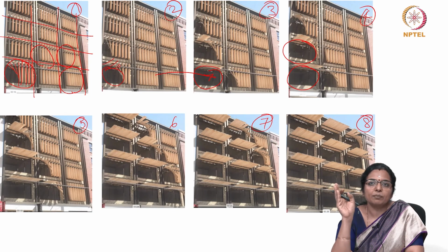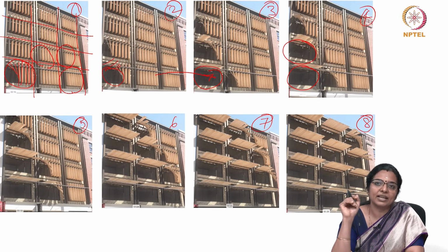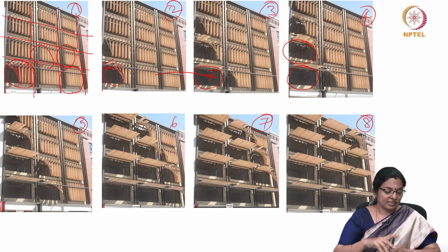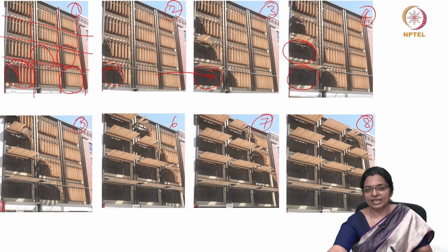So he solved this by having a series of vertical shading louvers that will move independently and pivot themselves to maximize solar protection. And when the sun reaches an altitude in which the vertical louvers will be ineffective, they completely rotate upwards to act as a horizontal shading element and a light shelf, which will also function to increase daylighting inside the building. So, this is a concept which was created by Tyler Short.